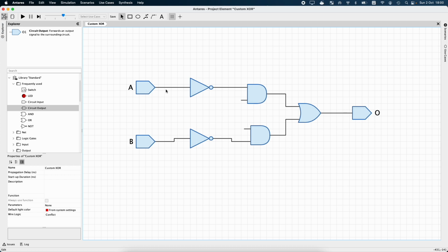To make a so-called wire junction, you have to press the Alt button while hovering over an existing wire. So press Alt, wait for the green connection highlighter, and press the left mouse button, drag the mouse while holding the left mouse button to your target pin, and then release the left mouse button.